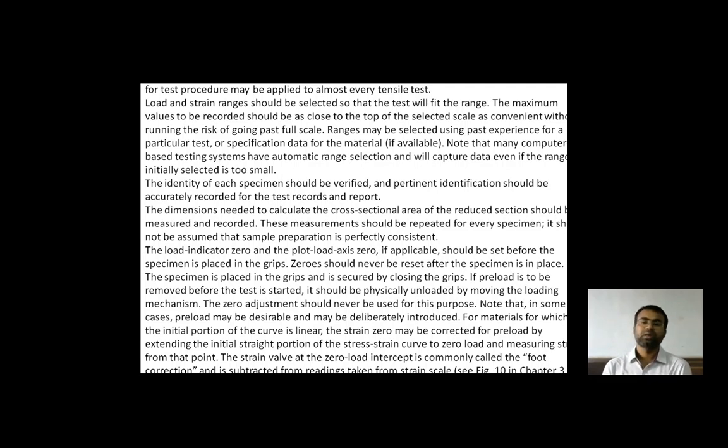Closing the grid. So if preload is to be removed before the test is started, it should be physically unloaded by moving the loading mechanism. So the zero adjustment should never be used for this purpose. Note that in some cases, preload may be desirable and may be deliberately introduced.